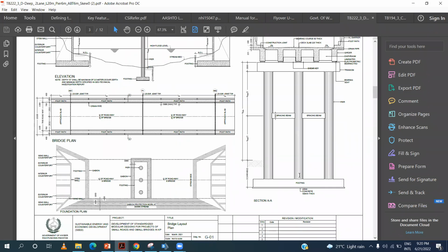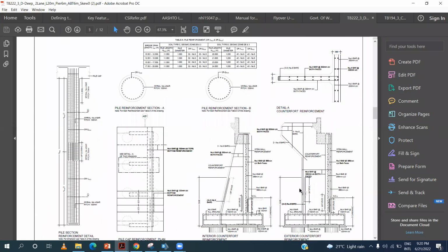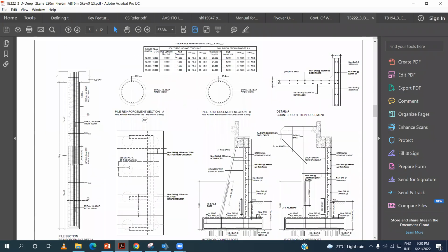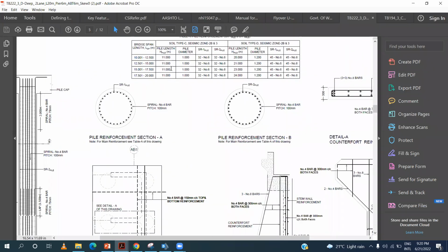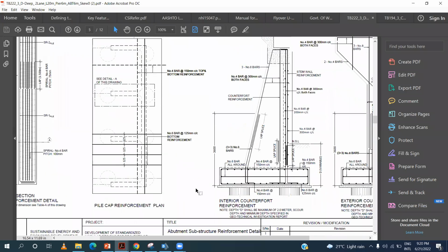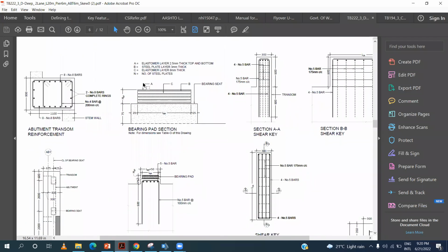When you get these location loads, the manufacturer will provide you a brochure in which they have mentioned the bearing size with respect to the loads. So you will decide from the brochure what depth you should choose for the bearing, and how many layers of steel and elastomer should be present in your bearing pad.